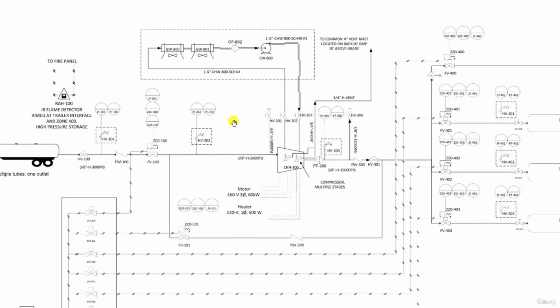For additional safety, the operator should continue to monitor the system during the work. In case of any even small leakage through the open drain valve, the maintenance work should be stopped immediately and the drain valve closed.